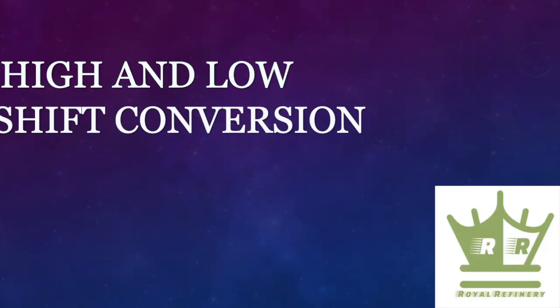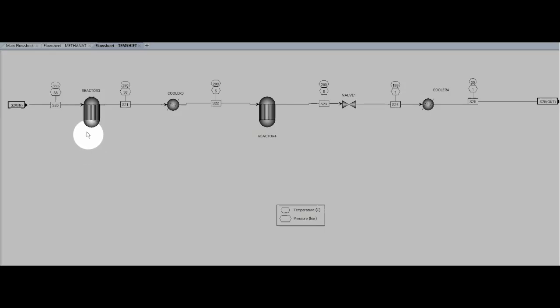Shift conversion. This step converts unreacted carbon monoxide to carbon dioxide to avoid the poisoning of catalysts using two reactors. The HTS is operated at 3.8 megapascals and a temperature of 350 degrees Celsius. The LTS is operated at 0.5 megapascals and 210 degrees Celsius. PRBM is used as RKS and PR do not give reliable results for the HTS. As kinetic data is not available and the reactions for the stage are at equilibrium, the RGibbs model was chosen for both reactors as it provides accurate results without the need for detailed stoichiometry.